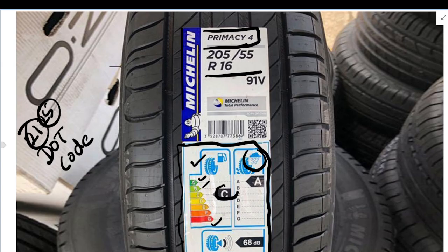And also, this is more towards the comfort. These two are more towards the handling and safety, and also the fuel efficiency, which is more important. And for customers oriented towards comfort or the noise levels, they also write the noise emitted by this single tire from the sidewall. So what if a user stands and there is a sidewall radiation of noise? This is also measured as per a specific condition, which we will deep dive into in today's video. But this is called a pass-by noise label.